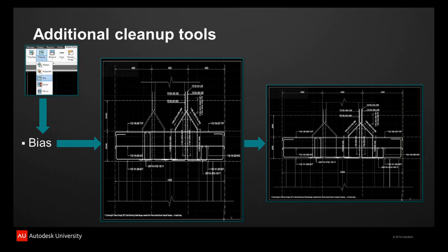What I actually did, and this is in the handout, you'll see it there, is I created a couple of AutoCAD temporary lines, and I spaced them using the dimensions I've got in the raster image. I drew one line, and I used the raster snap tool to position that vertical line directly on the grid line that I've got in the image. I then offset that line 4,000 millimeters, and I did the same for the opposite direction. That I could use as a base and a reference.